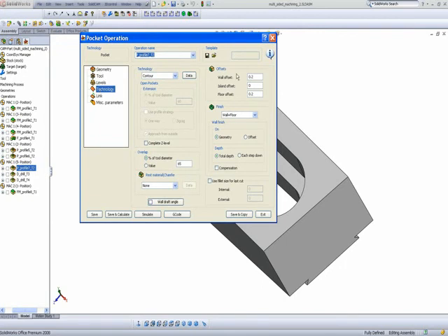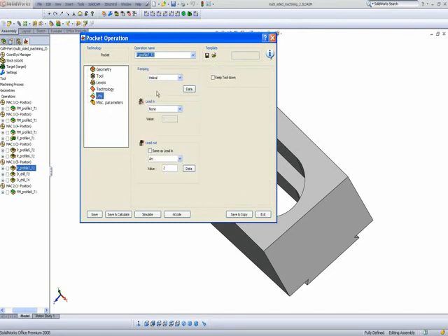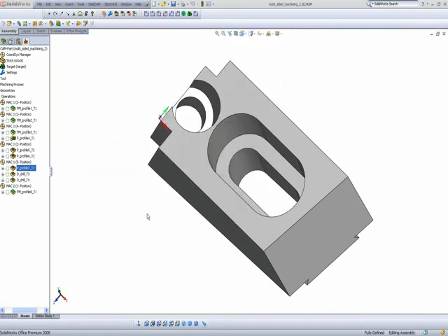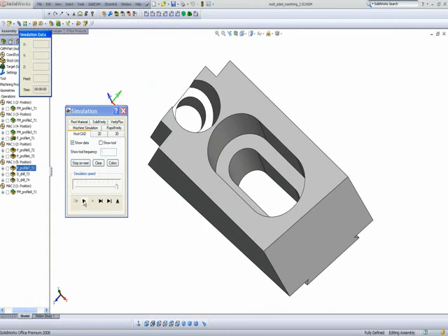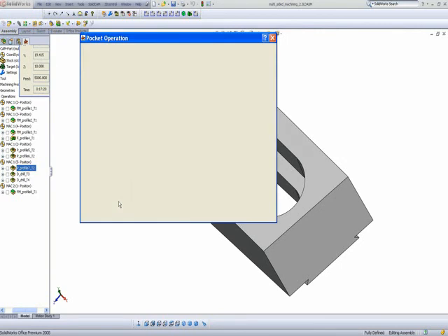Technology, again the same thing as I've done before when I had a floor at the bottom of 0.2 millimeters with a wall and floor offset, and again link ramping in with a helical and out with an arc. My simulation right down the middle, as we saw.